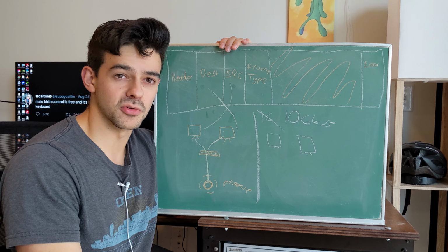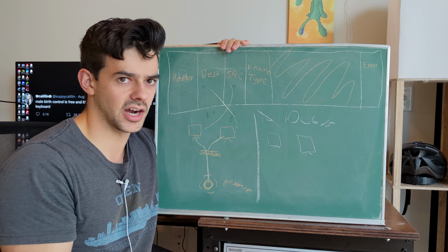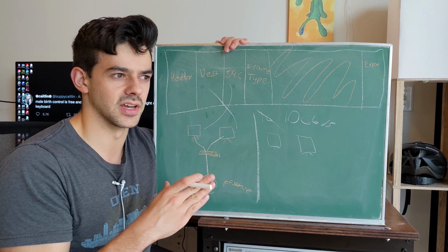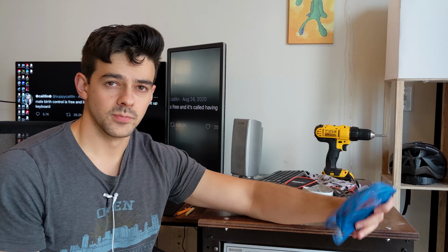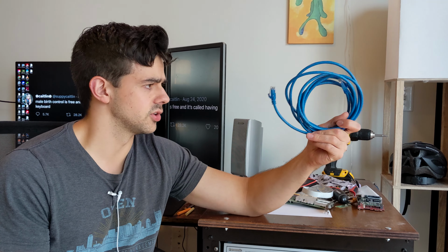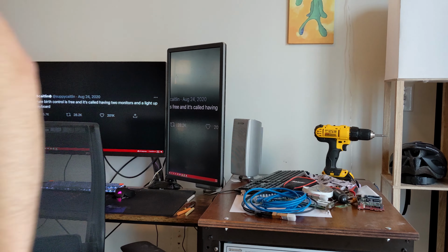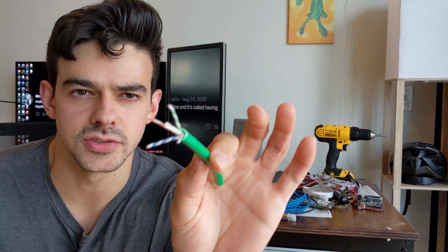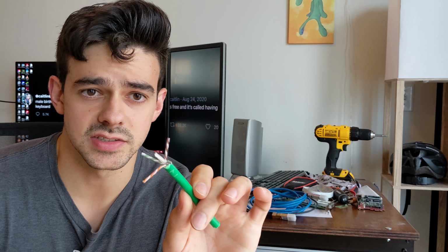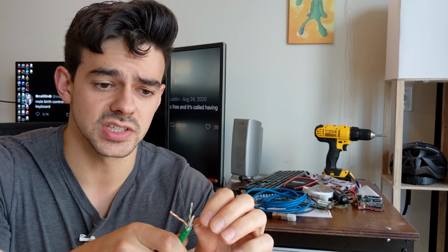And this direct attached copper will follow the SFP Plus protocol, which, in essence, if you're looking at IEEE standards, there's not much difference in the actual data transmission protocol, but the difference, of course, is in the signaling. In a traditional Ethernet cable, you know, your Cat 5, 6s, 7s, all of that stuff, there are 8 twisted pair connectors. Let me get you an open cable to show you. They look something like this. So you see there, these twisted cables. This, by the way, is Cat 6A cable. There's a bit of shielding in here. These wires are shielded. And it looks like this.